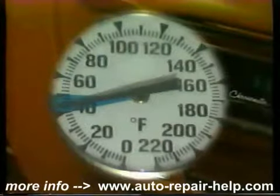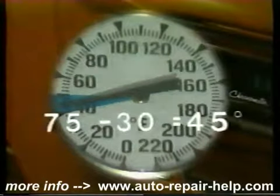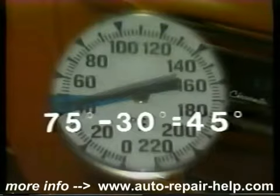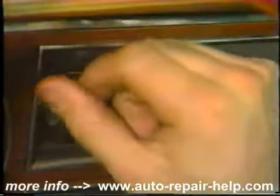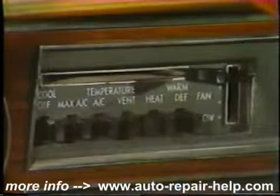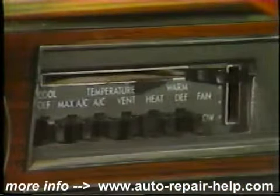As a general rule, on a good system, the air duct temperature will be 30 degrees Fahrenheit less than the ambient temperature. This functional test will tell you if the problem is related to the vacuum system, the electrical system, or the refrigeration system.